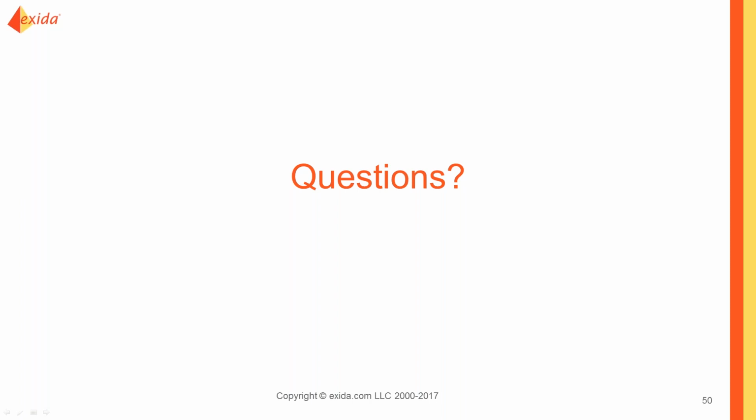understanding the question correctly, so I'm envisioning a SIF that only needs to be functional when the train is open or in use. So that SIF is going to have an overall probability of failure, and the PFD is the average probability at an instant of time that it's not available. So that SIF isn't changing, but it only needs to work 20 out of however many hours there are in the month. So I would put the modifier as a use factor. I put that as a modifier, or a use factor or a time at risk factor in the LOPA.